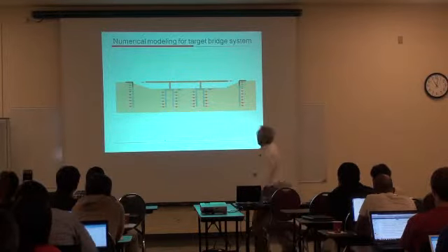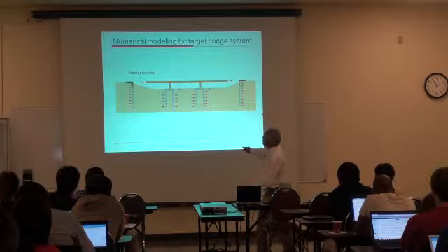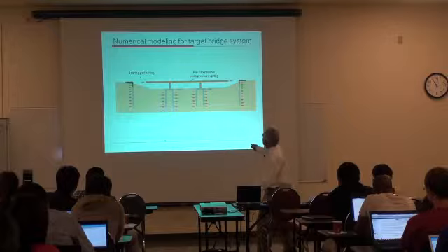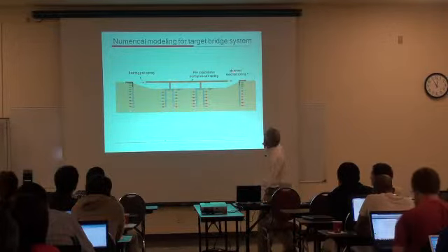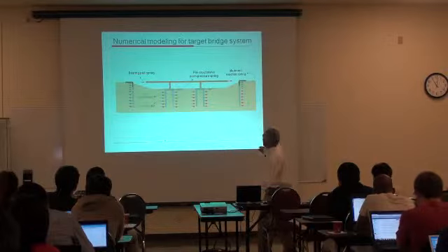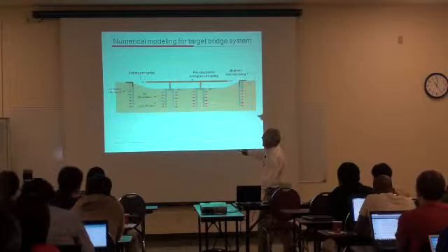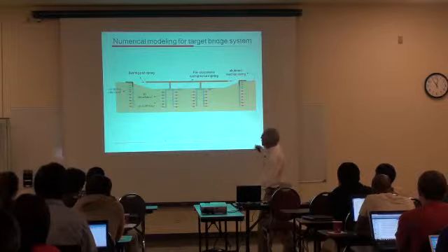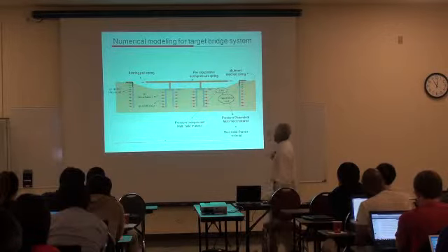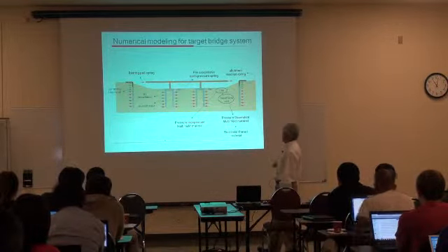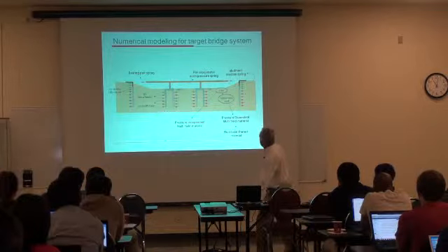So we use a bearing spring to represent the bearing pad, nonlinear. Also some nonlinear spring for the pile cap. Also some abutment reaction spring. And PY liquefiable and PY for the stiff clays. And also for the dry sand using the elements in OpenSees. For the clay, we use the pressure-independent material. For the sand and the liquefiable soil, we use the pressure-dependent multi-yield material.